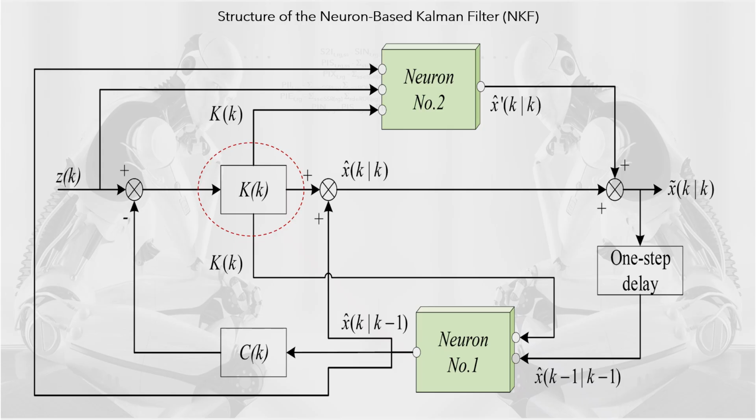The idea is to use the hybrid filter to estimate the K-matrix. KF and artificial neural networks, ANN, are combined in a tight pattern, in which ANN is applied during the internal filtering procedure. Lee et al. proved that the gain of the extended Kalman filter, EKF, is modified with erroneous measurements, which reduces the accuracy of the gain. Therefore they used ANN to train the gain with the input of the measurement, estimation and error, and it increased the accuracy. In NKF the critical components are the neural units that help to determine the intermediate variables to support the final filtering result.